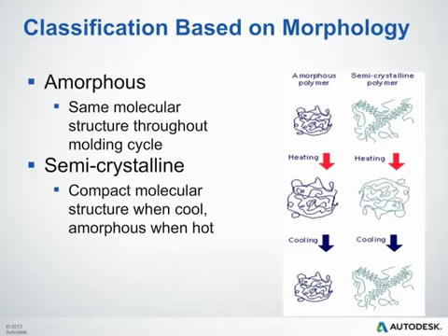This can be very important for our mechanical properties, but the most obvious effect you can see is in the clarity. The higher the degree of crystallinity, naturally the more crystals that have formed, and the less light will pass through that polymer. So it's directly affected by crystallinity, even from a visual aspect.